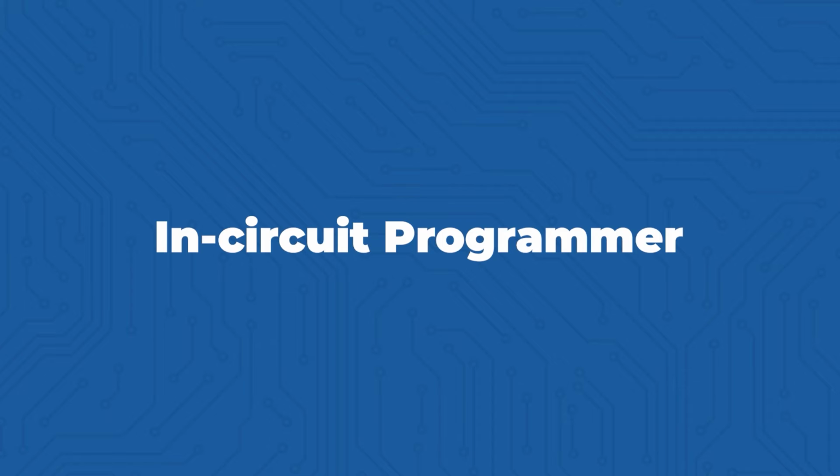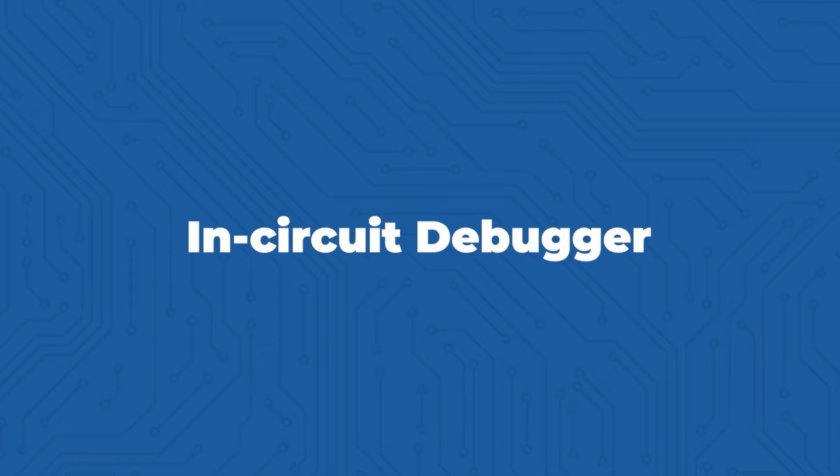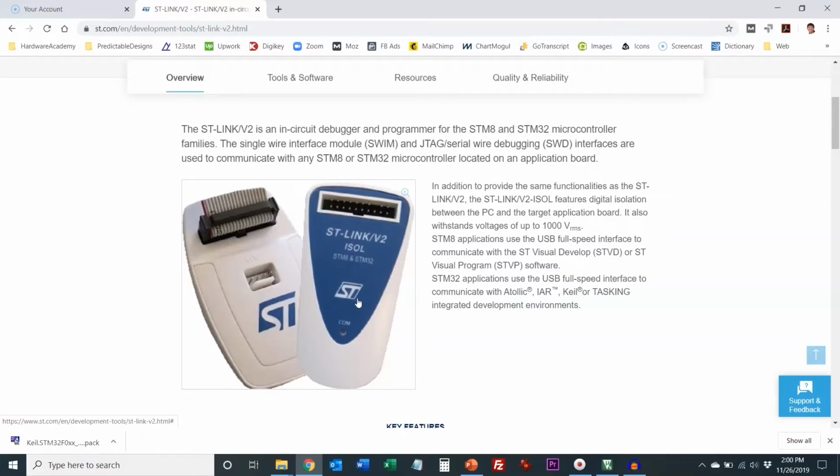But for most products, when you're designing a custom product with a microcontroller, you're going to need what's called an in-circuit programmer or in-circuit debugger. And it looks like this. This is one that's common for the STM8 and STM32 series of microcontrollers from ST Microelectronics. It's called the ST-Link, and you can see it's basically just a little, once again called an in-circuit debugger or in-circuit programmer.